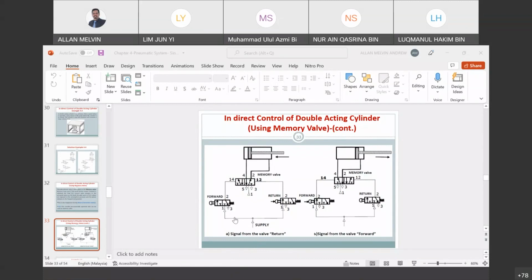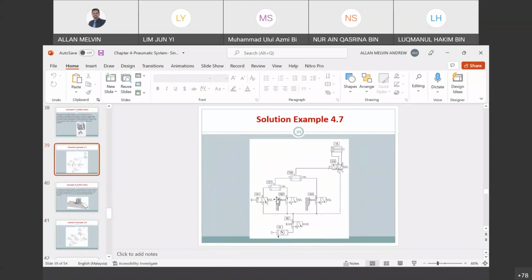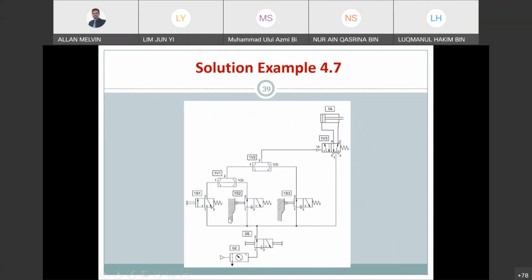Okay. So what are the stripes beside the roller valve symbol? What are the stripes here? The black ones, the lines. What is that? The lines here. Roller to activate. So the roller is activated. If you have this symbol with a line at the side, it means your roller is on by default. So this one is on, unless it is disconnected. There is one more.